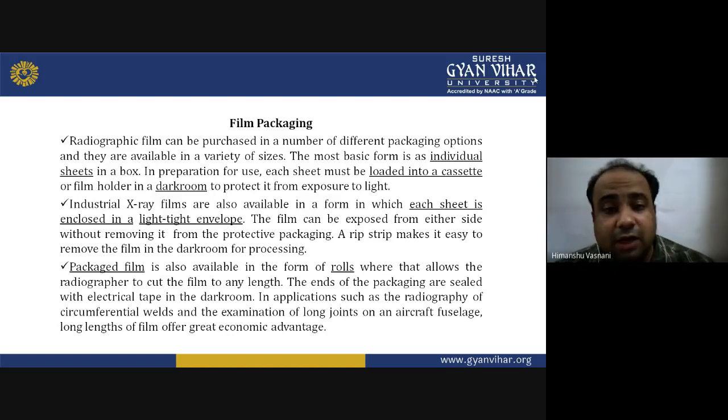Industrial X-ray films are also available in a form in which each sheet is enclosed in a light tight envelope. I repeat once again because this is a matter of concern. The film can be exposed from either side without removing it from the protective packaging. A rip strip makes it easy to remove the film in the darkroom for processing.